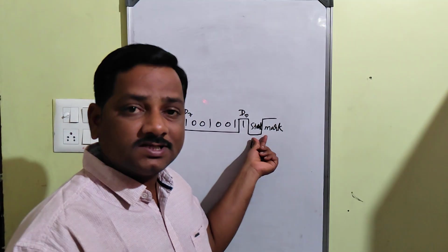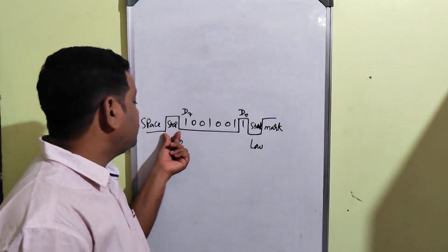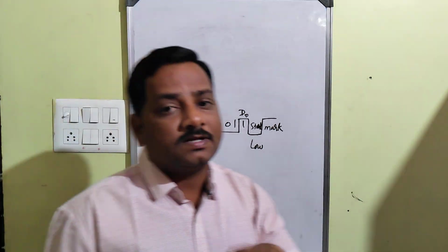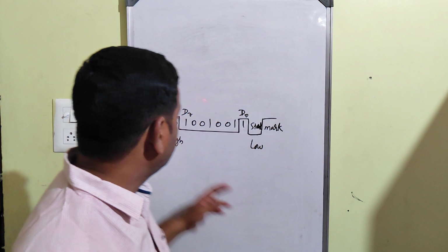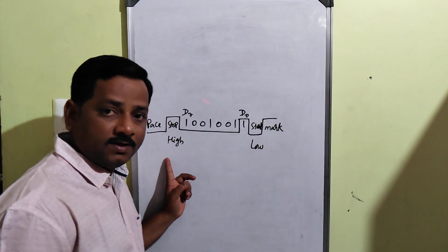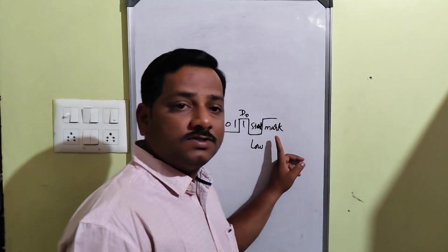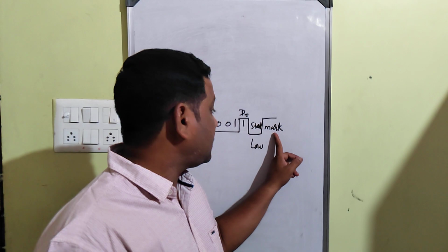Okay, it will have one start bit, and MSB D7 will be followed with a stop bit. That may be 1 or 2. It again depends upon the manufacturer. Okay. So now I have shown just one stop bit, and that stop bit should be high and followed with a low bit, that is space. And here it has been preceding the mark, that is high here.